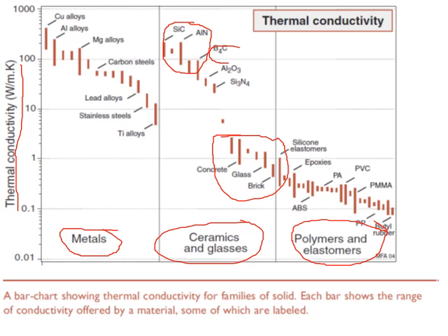And then you have the polymer and elastomer. As you know, this one is completely non-crystalline. So obviously you have a very low conductivity. The highest one is the silicone elastomer, and the lowest one is the butyl rubber. So mostly the polymers and elastomers are considered as insulators.